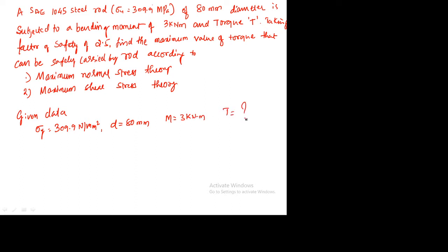Torque T you need to find out, and FOS is given, 2.5. Based on the diameter, you can calculate the bending stress, that is sigma x.